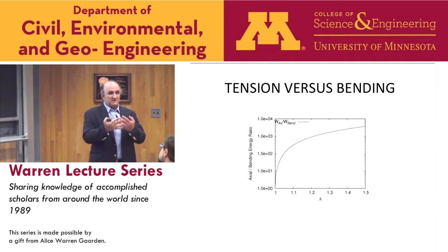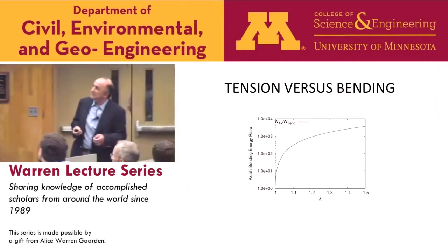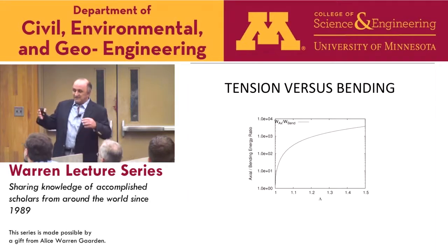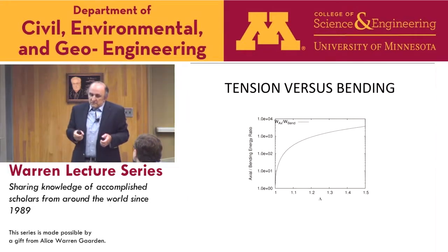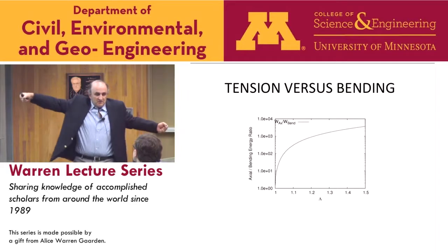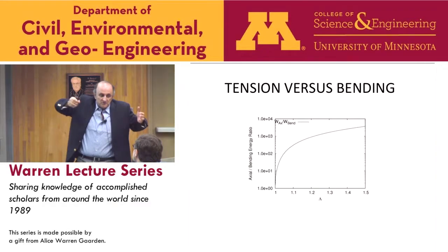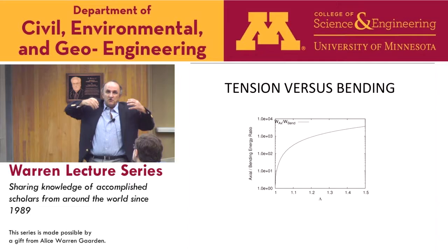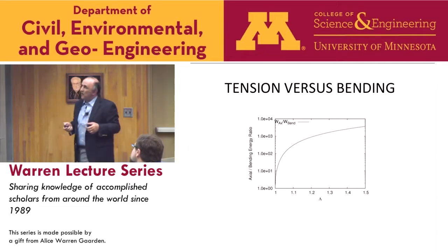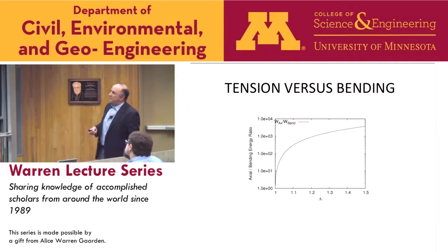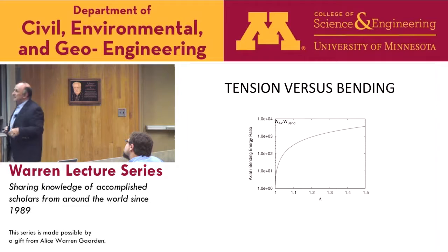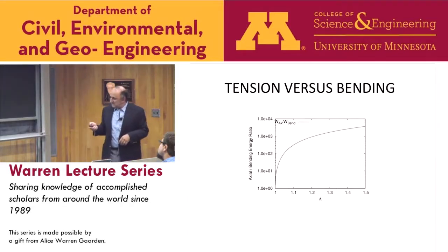So I mentioned that this is a frame. A frame is dominated by bending energy. There is no question about it. But this is a weird frame in the sense that these guys are very flexible. They actually have some tortuosity. And what they do, they realign themselves in such a way that you pretty much stretch a bunch of straight fibers in uniaxial tension. Another bunch of fibers actually not only doesn't work, it tends to buckle. And so it very quickly reconfigures itself from a frame-like structure to essentially a bunch of power lines that transmit axial stresses, line stresses, and the rest of it is not functioning.